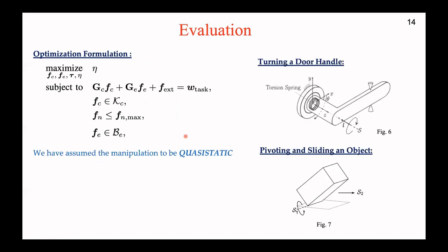We have evaluated our proposed metric for two scenarios. In both cases, we want to generate a constant screw motion along a given axis S by applying a wrench along the same axis. For simplicity purposes, we have not considered the manipulator joint torque constraints in our formulation. In both cases, our objective is to evaluate different contact locations based on the value of our task-dependent metric.